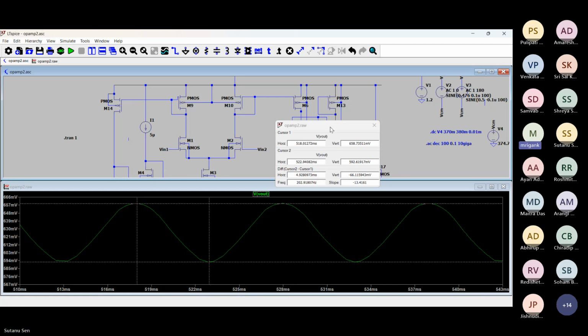Because of that limited gain of the first stage, it's possible that it is basically because the two paths are having asymmetry, and even the gain of the second stage on the left hand side is also less. Most of the gain is coming from the output stage. Yes. Because most of the gain is coming from the output stage, a difference in the DC level input of the first stage is not translating so much to a difference in small signal currents.